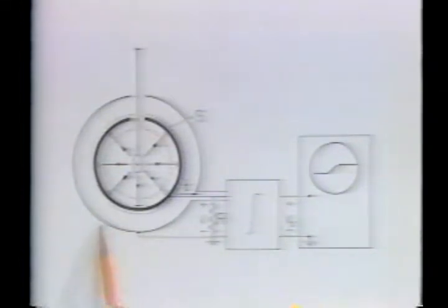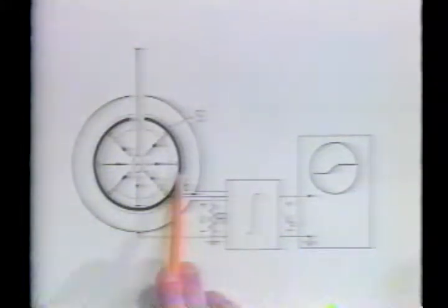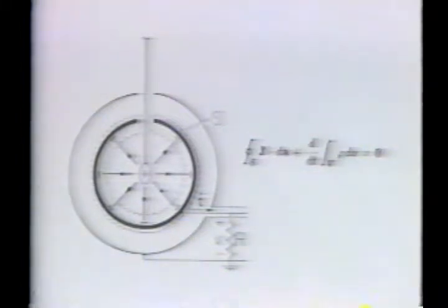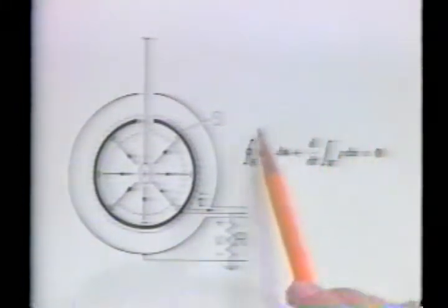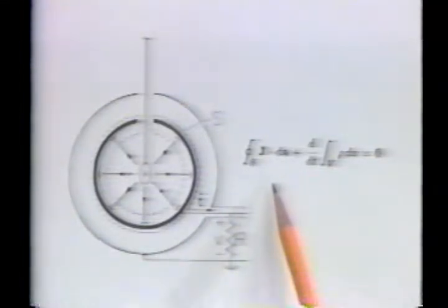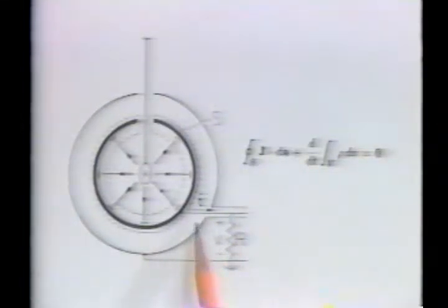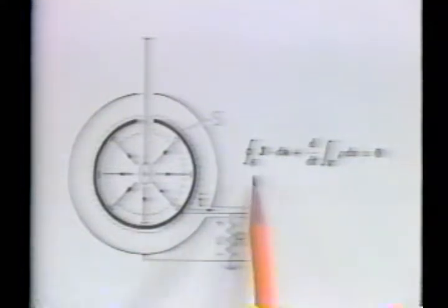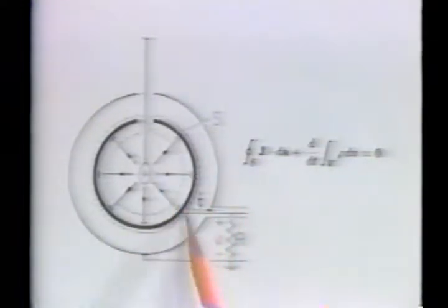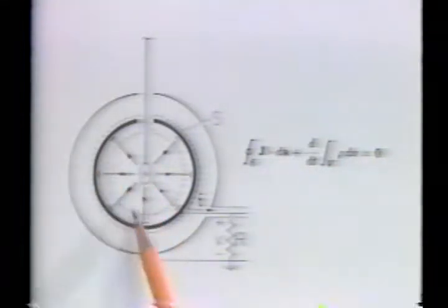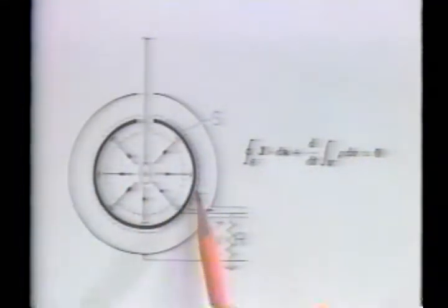Because the enclosure has little electric field between it and its shield, the integral form of charge conservation shows how the charge induced on the Faraday cage is related to the current I to the integrator. The surface S encloses the cage completely and cuts through the wire. The only contribution to the integral of the current density is where the wire passes through the surface and is the current I.